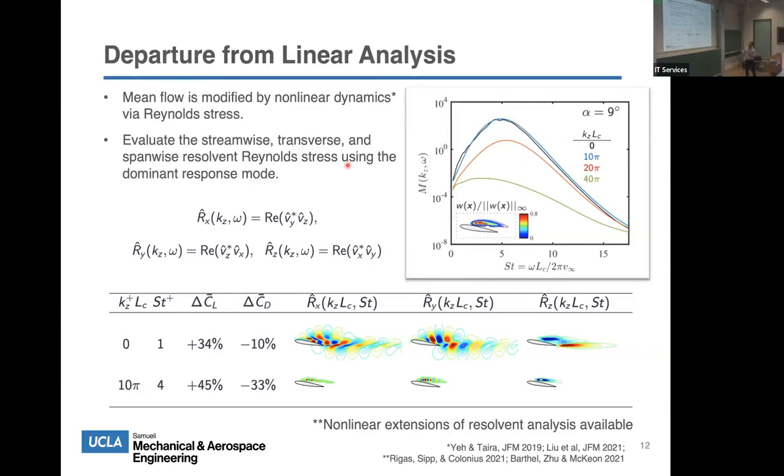Now, what we did here is that we assessed this Reynolds stress over the wing. We have a window here, and then said, okay, can we integrate that and see what that metric would be? So we have the 2D version, and the cases where the span-wise wave number is 10 pi, 20 pi, 40 pi. Now 2D doesn't really work because you're not going to get that three-dimensional mixing, so you can throw that out, although it's the highest. So then you can look at 10 pi and 20 pi being useful candidates, and maybe these frequencies. So this gives us some idea about where to go.